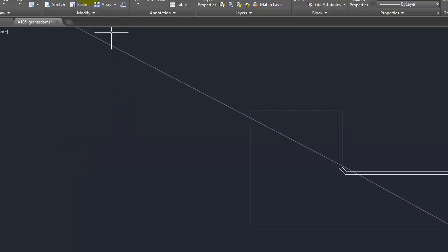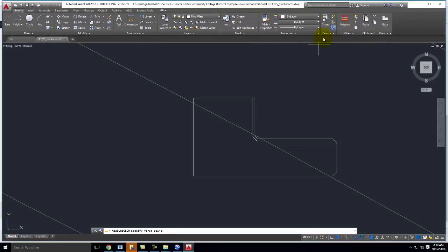Okay? So I want you to concentrate today on drawing out a floor plan and thinking about it. I had a question already this morning about how to check the square footage of a particular shape in AutoCAD. The good news is AutoCAD has a bunch of measuring tools that can help you calculate square footage. Right up here under Utilities, there's a measure tool. This measure tool will only give you a distance. So I could say, wait a minute, how far is it from here to here? And you can see, oh, there it is, 14'6". Okay?